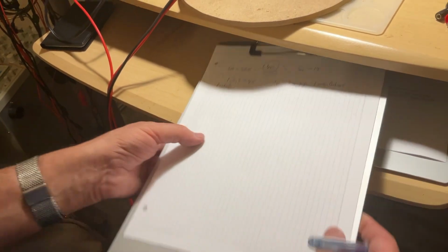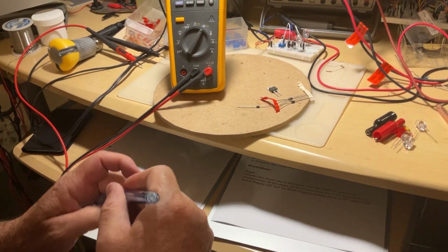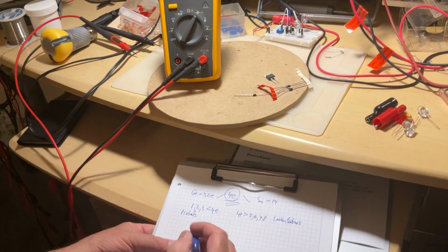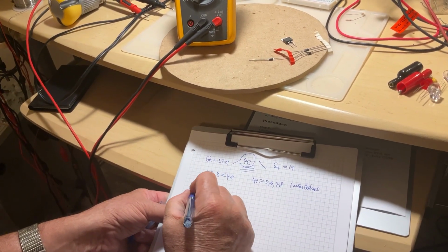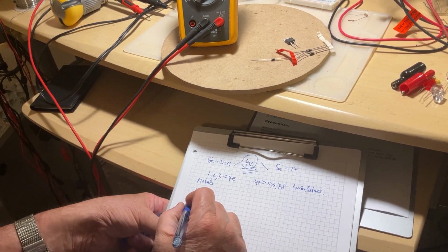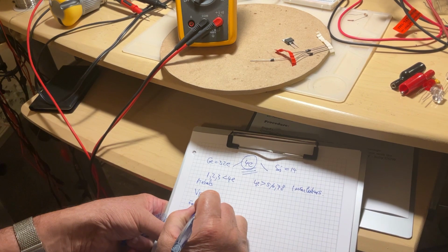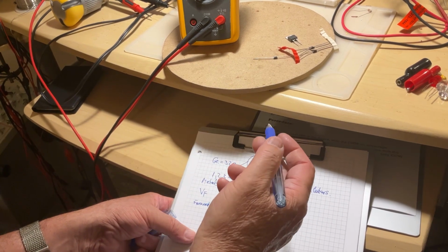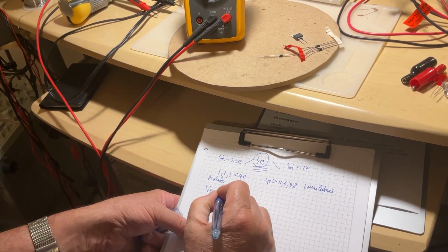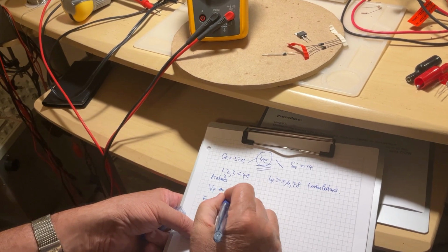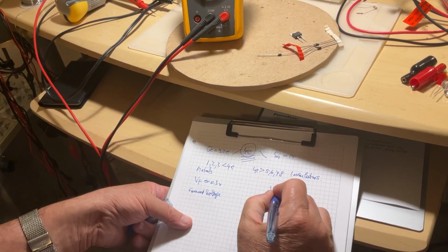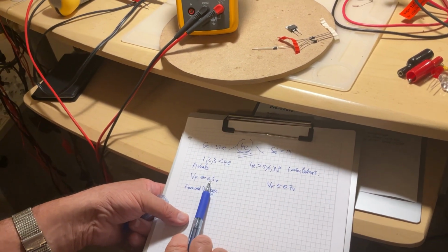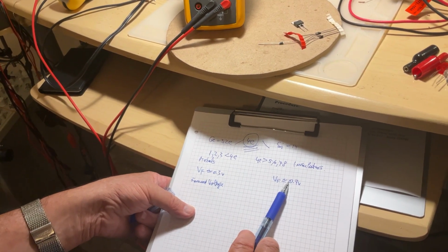Now, the thing about that is, when you measure a diode, a rectifier, you knew already something about VF, which is the forward voltage. So at what voltage does the diode start conducting? For the germanium it is around, let's say, 0.3, and for the silicon it is around 0.7. So it's lower for germanium and it's higher for silicon.